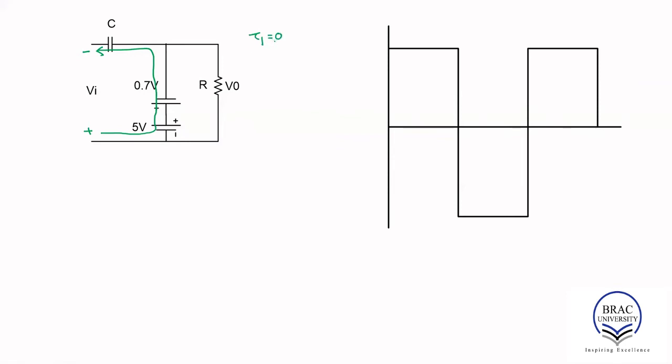So the capacitor will be charged up instantaneously, and it's going to develop a voltage across the capacitor, which we call Vc. We have already learned that we select the polarity of the capacitor voltage such that the terminal through which current is entering will be our positive terminal, and the terminal out of which the current is leaving will be our negative terminal.